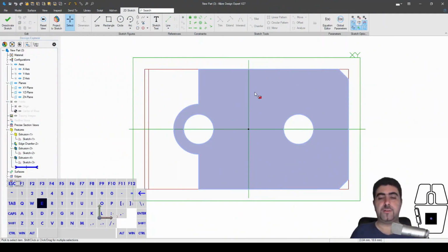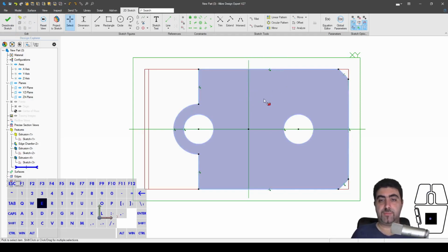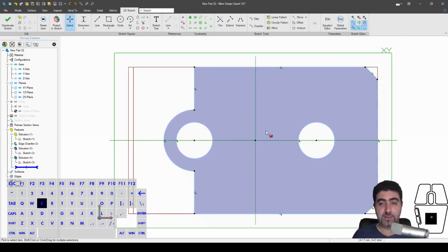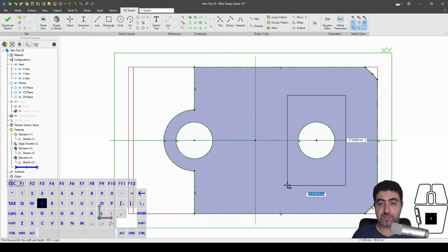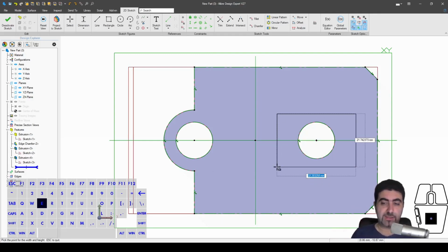Continuing on, there are a couple of interesting tricks in Alibre when it comes to dimensioning, apart from that diameter value. One is auto dimensioning. So I project everything in. I'm going to create a center rectangle around the center of this circle, of this hole. And I'm not going to click yet.